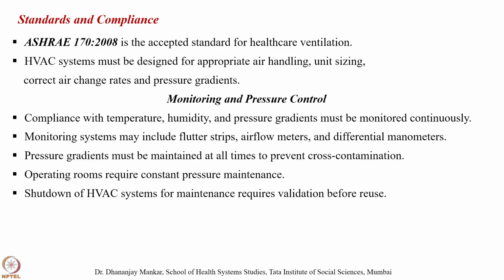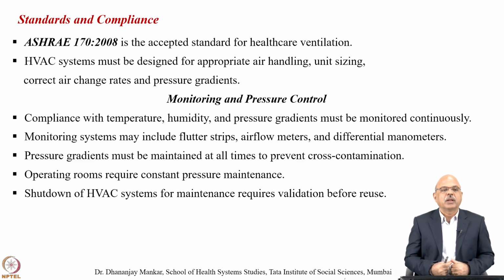Standards and compliance. As mentioned in the previous chapter, ASHRAE 170-2008 is the accepted standard for healthcare ventilation. You need to work on the HVAC system, which needs to be designed for appropriate air handling unit sizing, correct air change rates and pressure gradients.